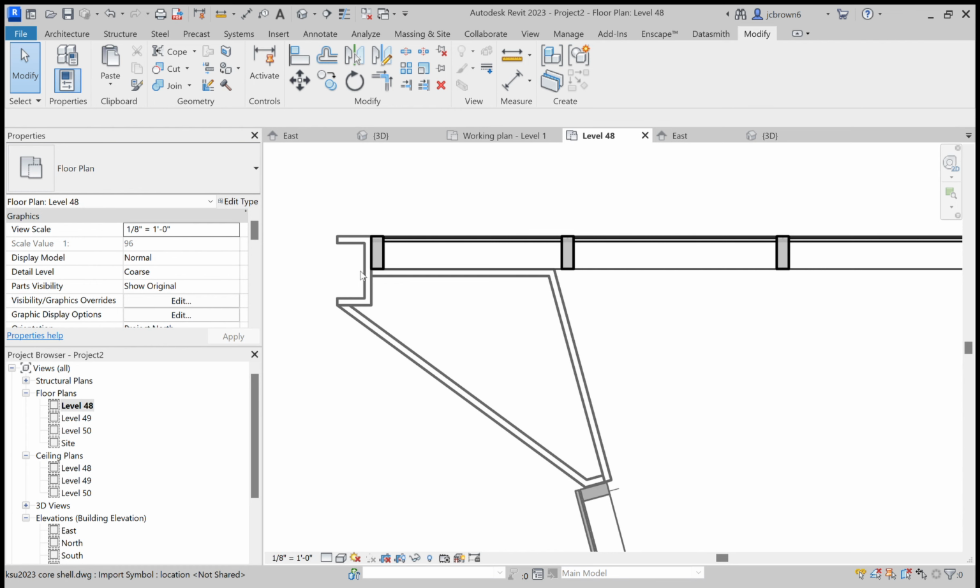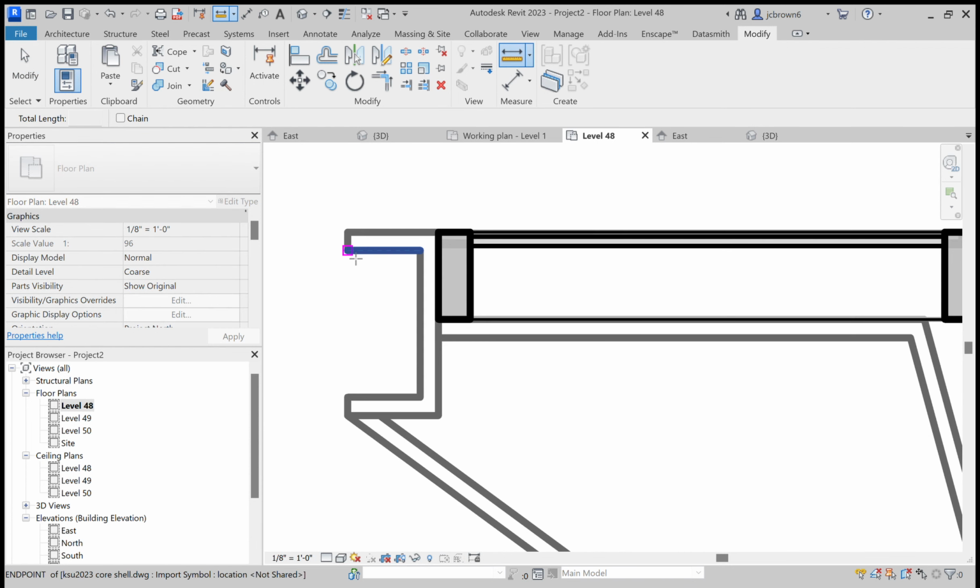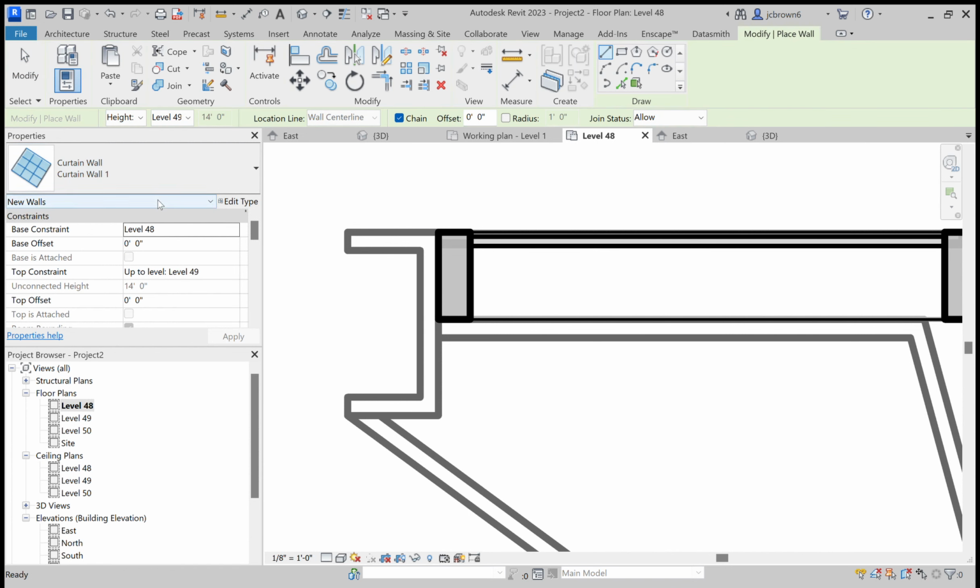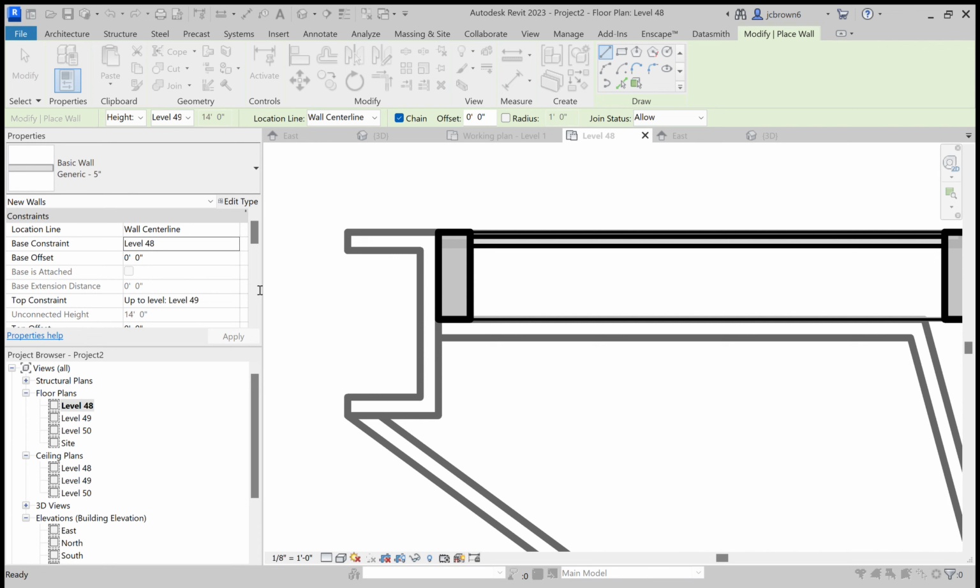So in the walls, what you're going to have to create, just like we did with the columns, you're going to have to use the default layers for the default settings that are there for the walls and modify them for the walls that we have. For this wall, I would just create, let's see how wide it is. It's 2 inches. So I would create under wall architectural, I would go here to maybe 5-inch generic, and I'm going to edit this and duplicate it, and I'm going to create a 2-inch metal wall. It's probably like a metal detail.